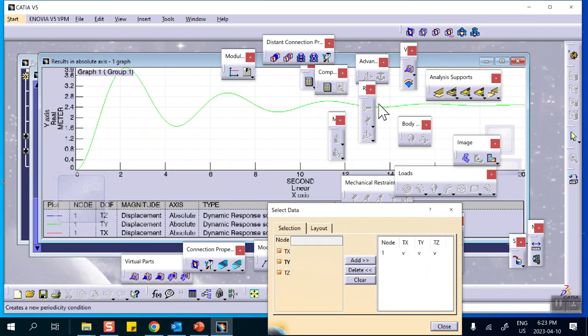Okay. So what I have done for you is did the problem as a static problem, inserted frequencies, inserted transient dynamics, and showed you how to get the graph of the displacement as a function of time. And there's a whole whack of things here that you can do, which I'm not going to do. You can try it on your own and see how good it's going to go. So yes, single degree of freedom system, we can do it very quickly, at least for the case of constant force, suddenly applied force.